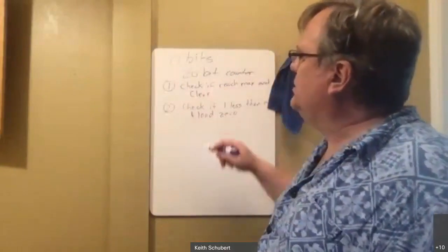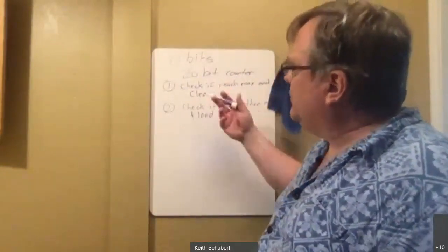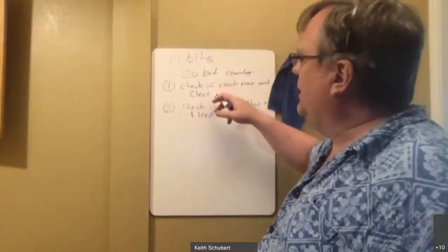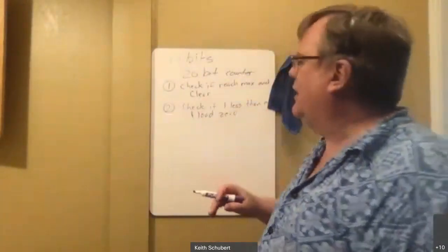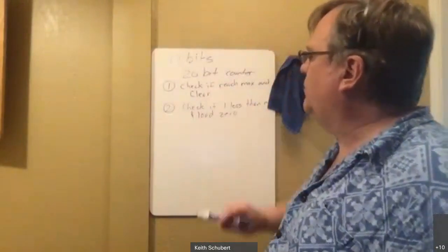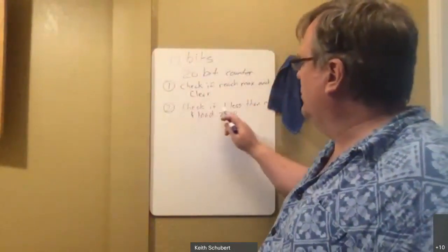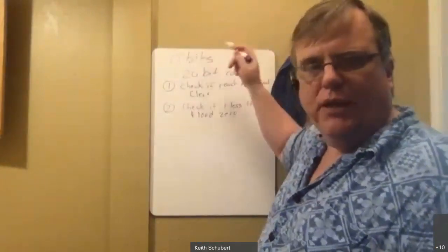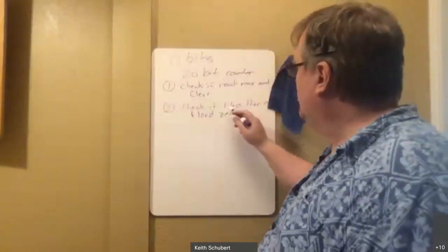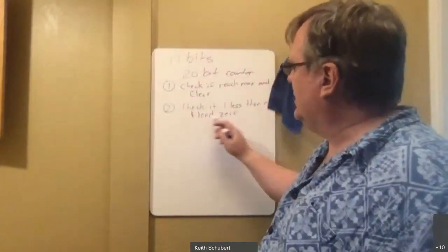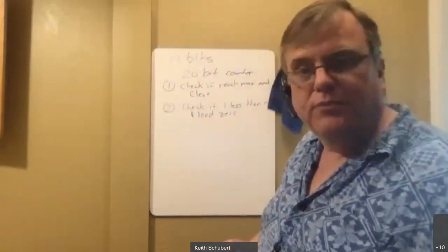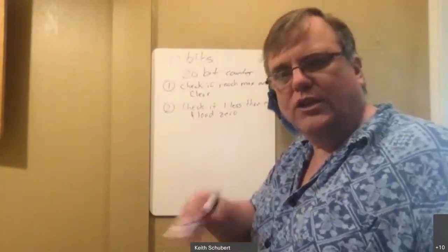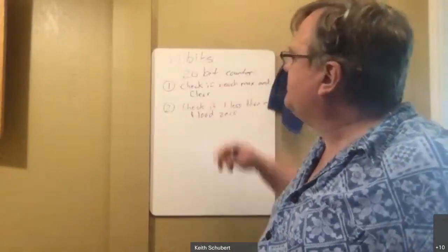That can cause a momentary glitch. It's pretty easy to build, and it relies on the asynchronous clear. It'll only be up for an instant, but it does provide a potential instantaneous thing. Some people will do this. The other way I can do it is see if I'm one less. Remember, 2 to the n minus 1. I could check just before that, and then on the next state, I could tell it to load a 0 in. So either of those would count, from what Carlos suggested, to set them to null.